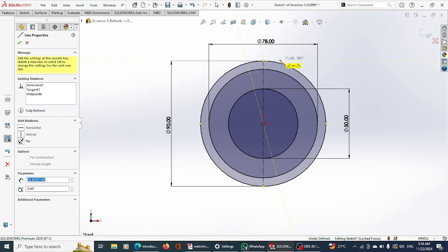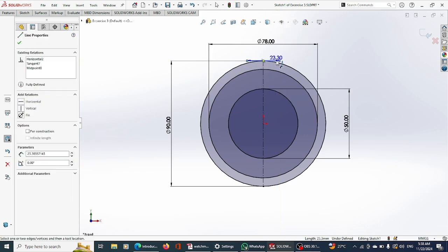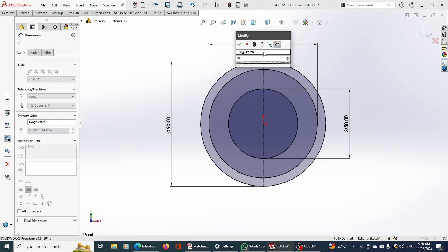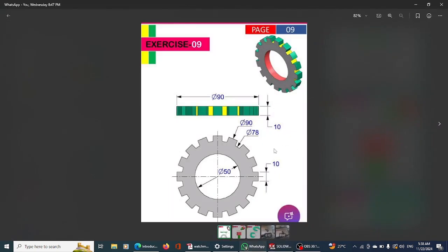So we click. Now pick my smart dimension tool. I don't even need to escape a tool to pick another tool. Shortcut. I choose that line. Now when you are working and you are in between many lines like this, don't worry, I'll still show you. You have to zoom in. So now this guy is 10. Remember, it was 10. I'll show you. Enter. 10. Good. See it here. It was 10, and all of them are like that at 10. So this guy is 10.